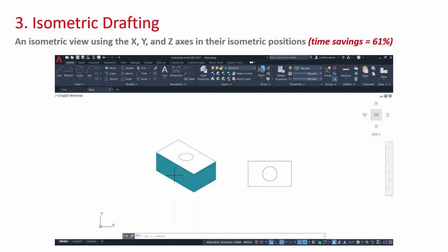So you can see there on the left, that is purely 2D drafting. There's a hatch pattern and there's some lines representing what looks like a rectangular base with a hole in it, and that's the ellipse that I mentioned. Now, if I start looking at IsoDraft there and switching on the status bar, can you see I'm changing the positions of the lines, the axes on the cursor, and that basically kind of works in an orthogonal kind of setting, because what it does is it ties you down to drawing lines at those angles in the IsoDraft to allow you to create that 2D representation of that isometric view of the base.